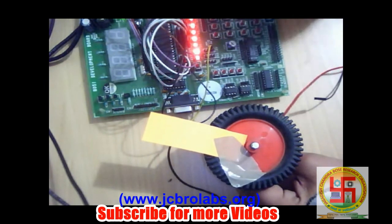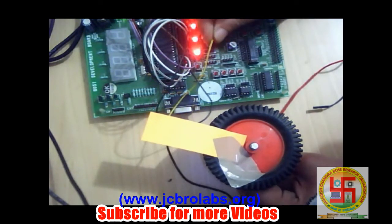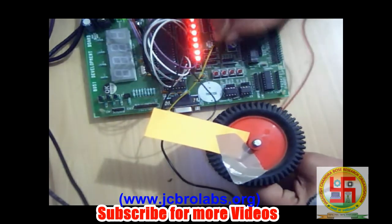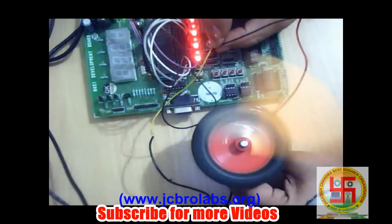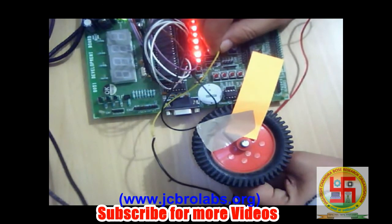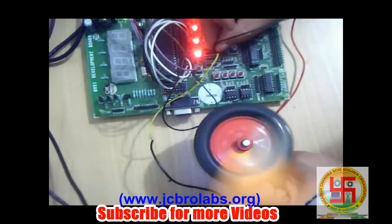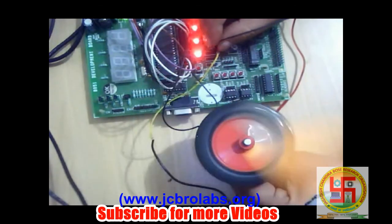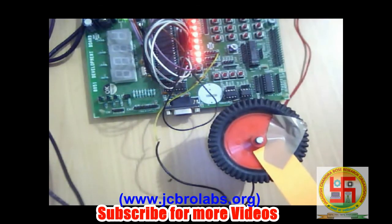So this is the DC motor, and these are the two terminals which we have connected to the supply. First we will connect this terminal at plus 12 and this terminal at ground, and we will see. Right now it's rotating in one direction, in a clockwise direction. Now we will change the polarity of the connections. One terminal will be grounded and the other terminal will be connected to the supply. Its direction of motion has changed, and now it is rotating anti-clockwise. So this is how simply we can change the direction of the DC motor, whether it is running in the clockwise or anti-clockwise direction, just by changing the polarity of the power supply connected to it.